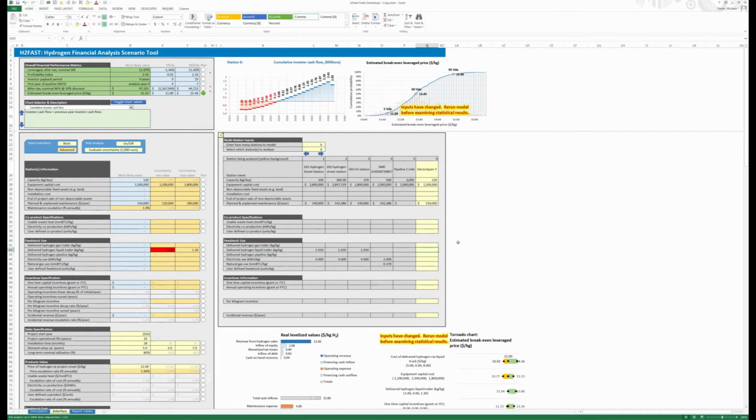Now for an electrolyzer, it wouldn't have any co-products, but it's going to use a lot more electricity. I've seen electrolyzers, completely retail, it might be closer to 70 kilowatt hours per kilogram. If it's just production, might be 60, 65. So let's just look at the production portion of the electrolyzer.